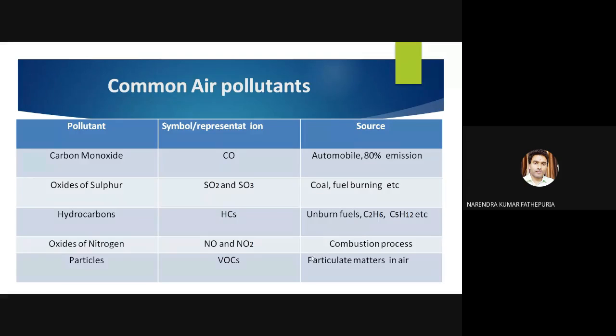100% combustion will not happen inside the internal combustion engine. So unburned fuel releases hydrocarbons, which will create a lot of problems. That's the main reason for the air pollution actually. Various oxides of nitrogen, NO, NOx and NO2, are released in the combustion process, along with particulate matter like volatile organic compounds, PM2.5 and PM10, and suspended particulate matter, also respirable suspended particulate matter.